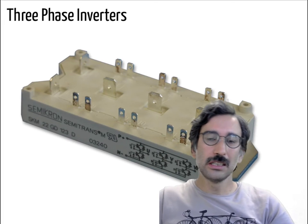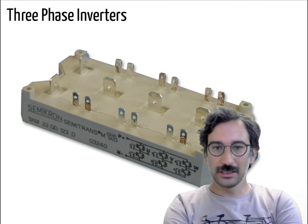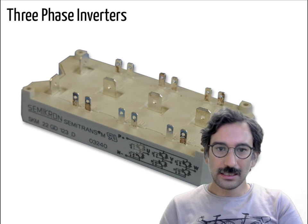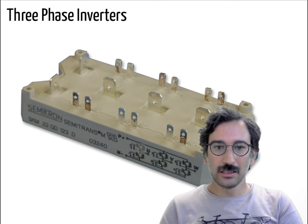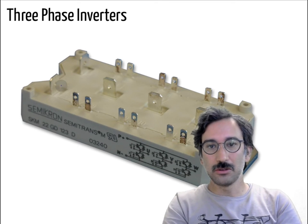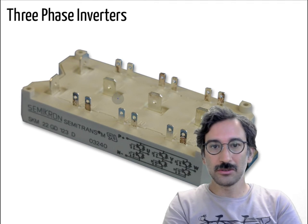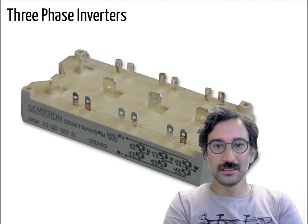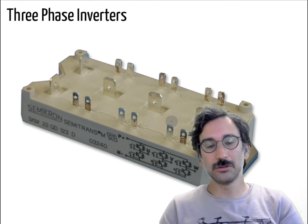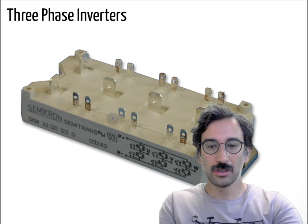Most of the three-phase inverters are made using that kind of modules. If you look carefully, you can see the equivalent circuit here. They are made of 6 transistors, and you can see the DC terminals. Probably these are the DC terminals, and these are the three-phase output, where you connect your motor or connect to the grid, etc. And the smaller pins are for controls or for measurements.